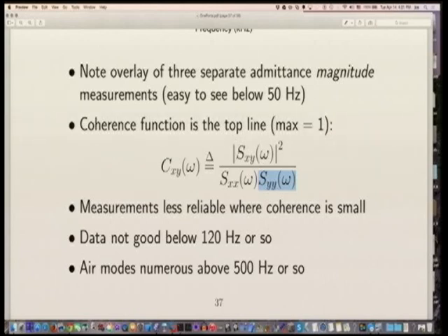And then the cross spectrum, we all know from 320, is the Fourier transform of the cross correlation. And so you cross correlate your input and output basically. And you also may remember that should be the impulse response. If you cross-correlate the input of a linear system with its output, you should see the impulse response as the result.